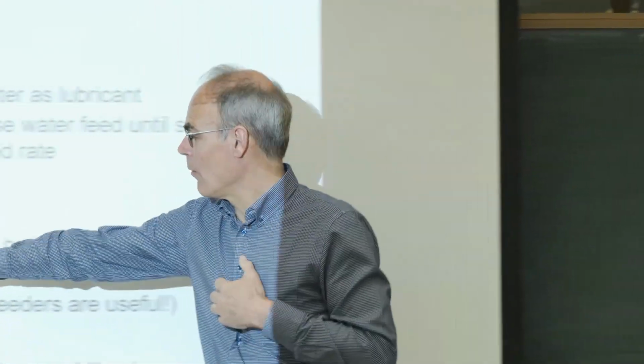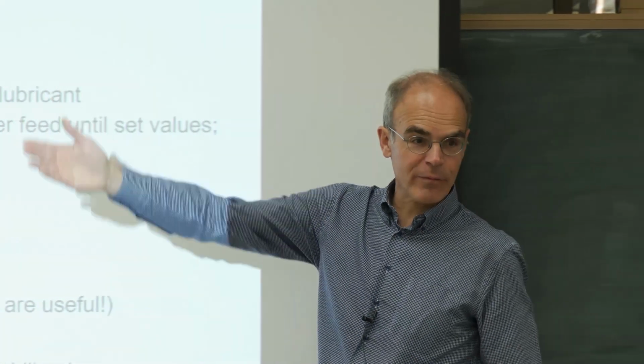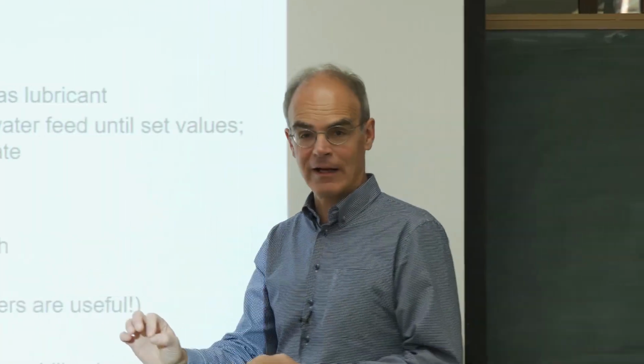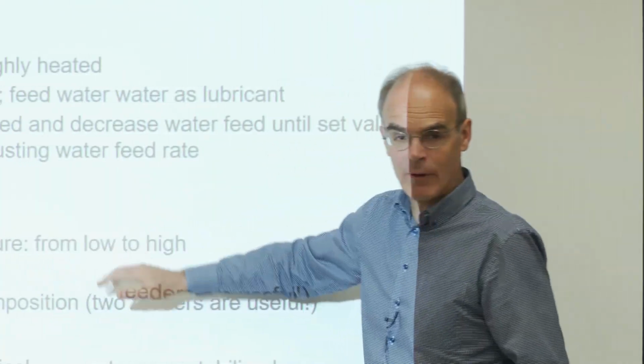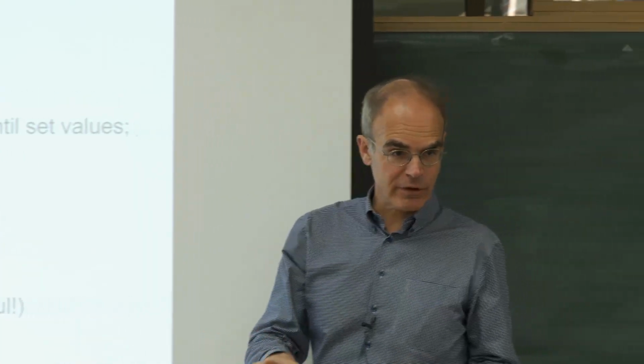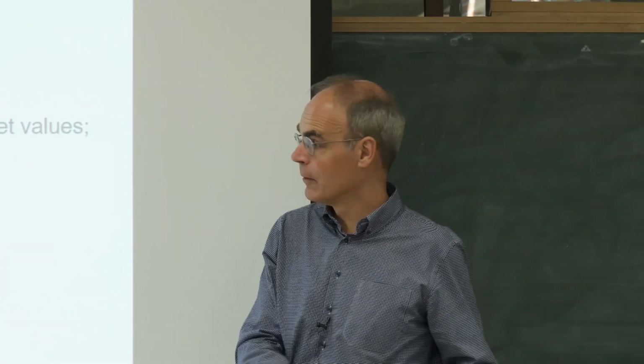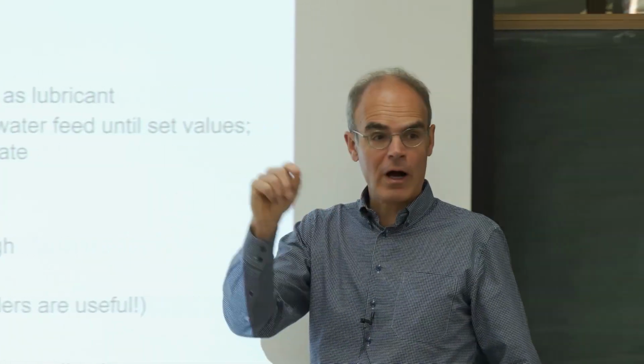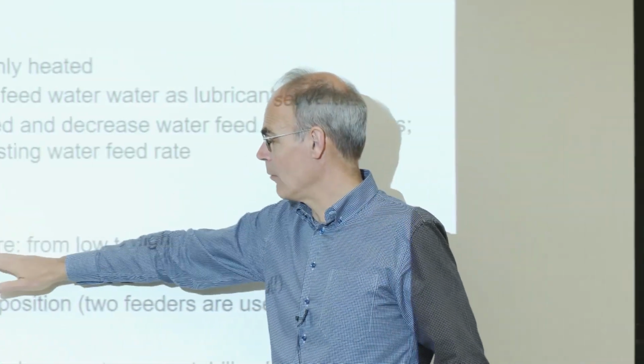So when you overshoot your temperature, someone can go take a coffee, take lunch, come back and try it again, because you heat up really quickly. The cooling down is very often somewhat slower, or sometimes very much slower. So if you want to do a temperature set from low to high, again, you can play with that.